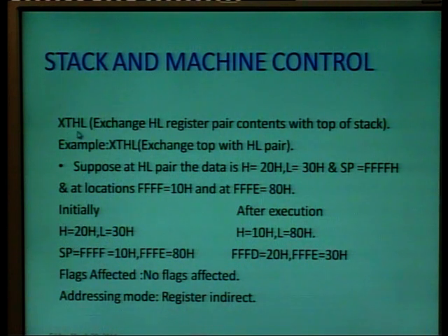XTHL, exchange top with HL: exchange the HL register pair content with the top of stack. The top two elements of the stack memory will be exchanged with the HL pair contents.